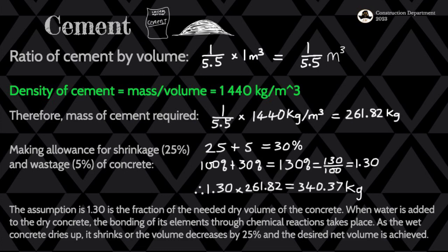And then you find that when we add the 3 numbers, 1 plus 1.5 plus 3, we'll get 5.5. So if you know how to calculate with the ratios, we know that cement is basically 1 over 5.5 of the total amount in the concrete. That's the fraction of cement in the concrete.